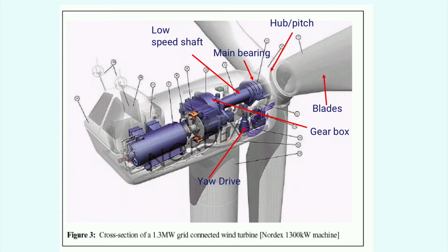A gearbox needs to be properly designed to withstand in-line and off-axis forces. If it is not properly aligned, then adverse wear can occur, which can result in premature failure. Lubrication is an important factor and must be efficiently maintained throughout operation.